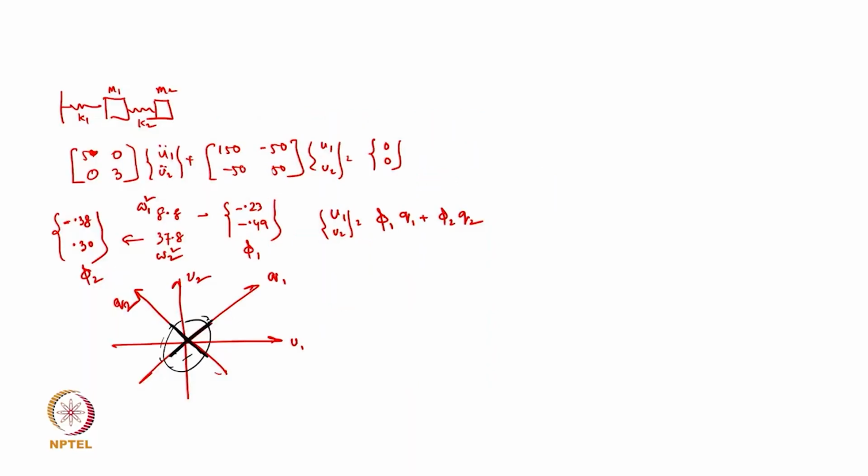Now if we are not considering that q2, then what are we doing? Because that is the case we just discussed. Let's say we are analyzing a 100-storied building, and we found that our mass participation is coming 95% in the first 5 modes.